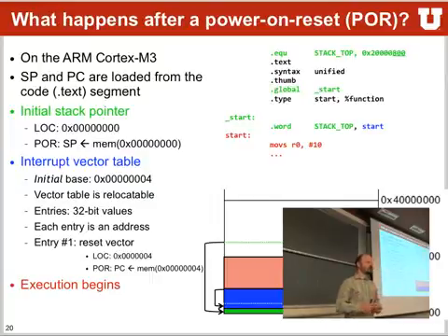The first one is it will read the stack pointer from memory address 0, and then read the next memory address, so 0x4, and jump and set the PC or the program counter to that particular value. So at location 0, it will store whatever is written in there into the stack pointer so that we know where the stack is sitting in our RAM. And the second address is it will go to this address, read it out, and will put the program counter to that value to start execution at the address stored in this memory location.